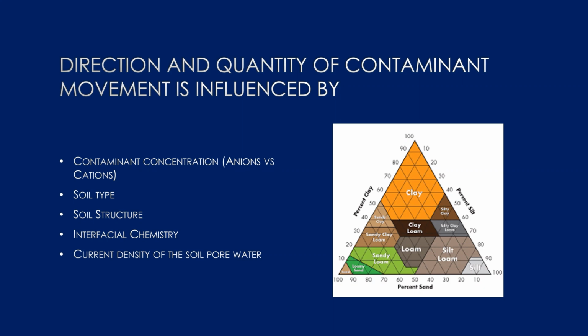Electrolytic methods can be used in saturated or unsaturated soil. However, experimental results indicate that there is a minimum moisture content at which electromigration can occur. This is related to and can be estimated from the residual moisture content of the soil. This is referred to as immobile water.